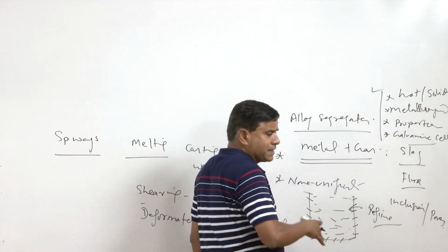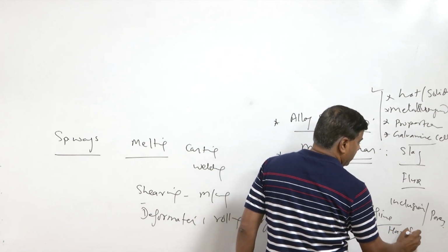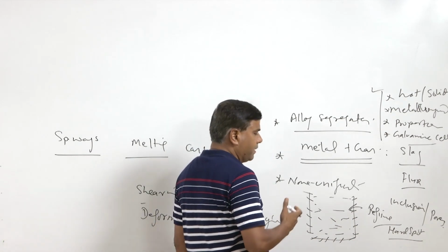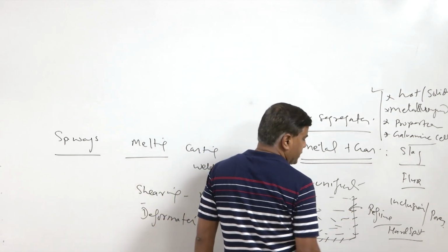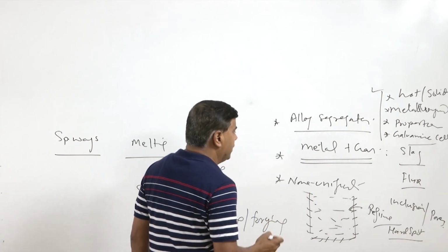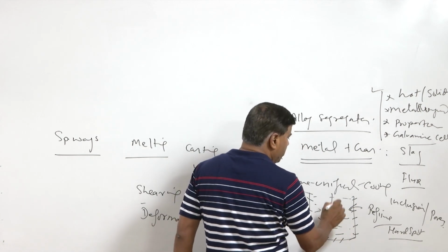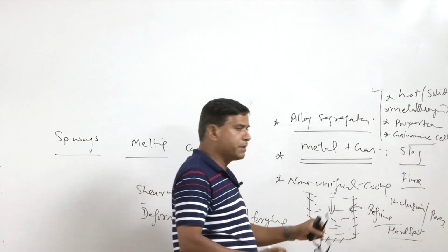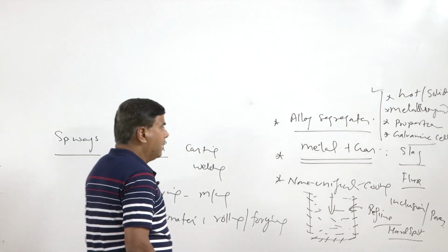But if the metal is hardenable, then it can lead to hard spot formation due to high hardenability or hard microconstituent formation tendency. So, apart from the refinement, hard spots can also be formed if the metal shows high hardenability due to the non-uniform cooling rate. We know that the core will be cooled at lower rates as compared to the surface zones, and this in turn brings a lot of heterogeneity in terms of grain structure and properties.